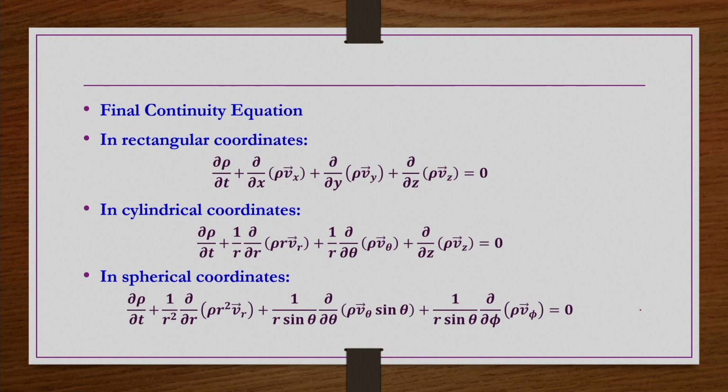So, the point of going through this continuity equation is that for any flow field you take and then try to solve, whether theoretically, using analytical expressions and approaches, or computational approaches, whatever you do, the final flow field that you get as a solution must satisfy the continuity equation. Only then can we say the solution is reliable if you are doing the solution at the microscopic level.